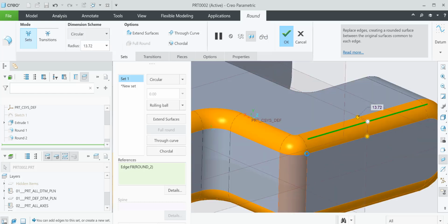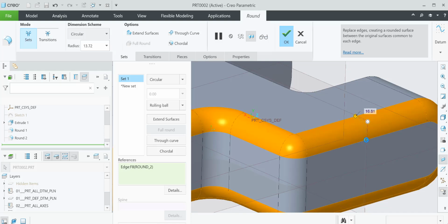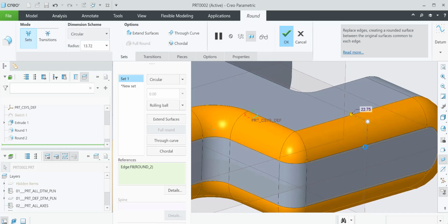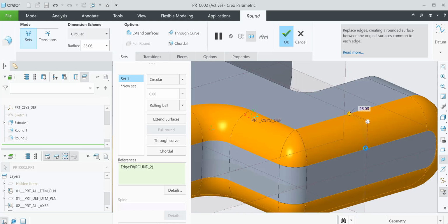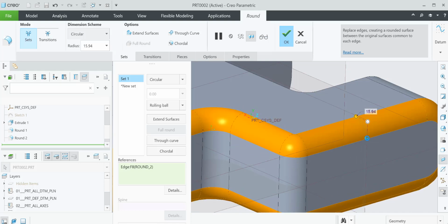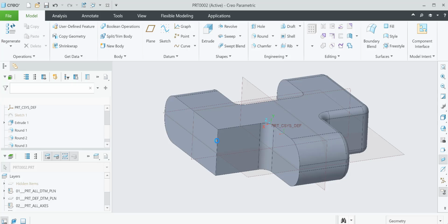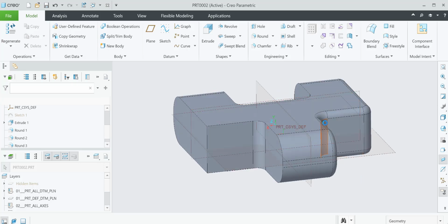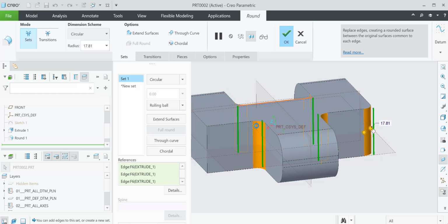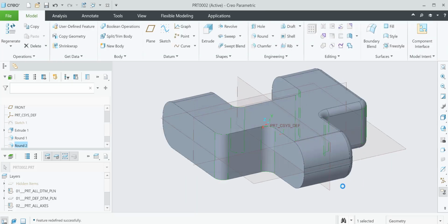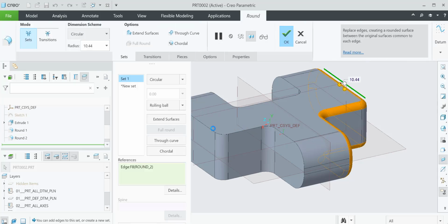watch how this geometry turns into a triangle. Yeah, I don't like the triangle because if you try to solve FEA underneath that, it's going to fail. Won't triangulate properly, or at least that's how it's always been in the past. Notice how I forgot to put one round here? You could just add one or redefine the other round and hold the control key down to pick the one you forgot. And look, they're all documented here in these references. You want to be mindful of those references, because when things start to fail in your geometry, it's usually that simple.